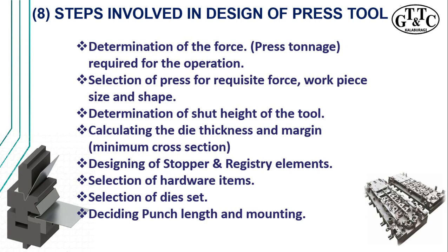And then here we come to the next slide. It is the steps involved. What are the steps you have to consider or think about before you start designing? You should plan before you start with the actual designing. The first one is determining the force, or you can call it the press tonnage required for the operation.